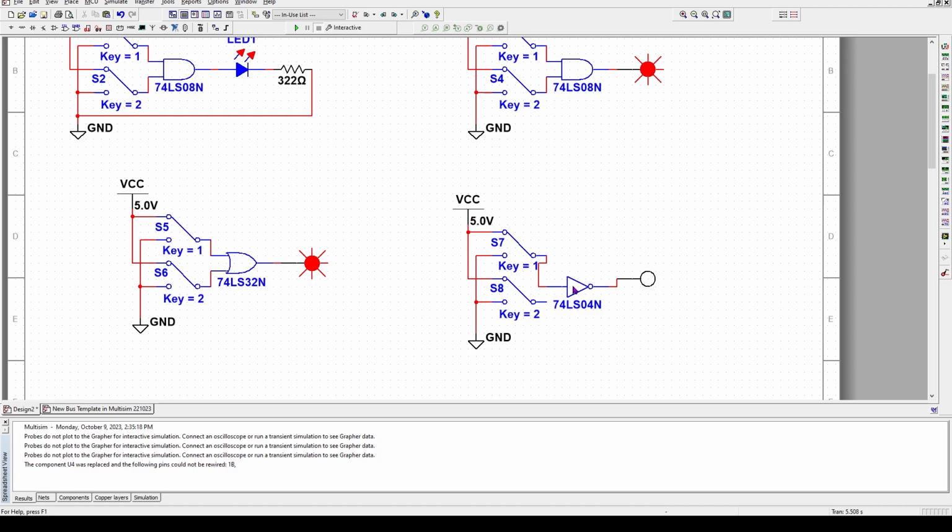Okay, so now I want to make this efficient again. So I'm going to click on that and bring it up here. Make sure there's one click of net or wire between these. I'm going to click on the probe coming up, clicking out. And now I've got that, but wait a minute. There's only one input on a NOT gate. What do we do with this thing? Well, that's easy. Kill it. There we go. So select it, delete it. It goes away. This NOT gate can be made more efficient now.